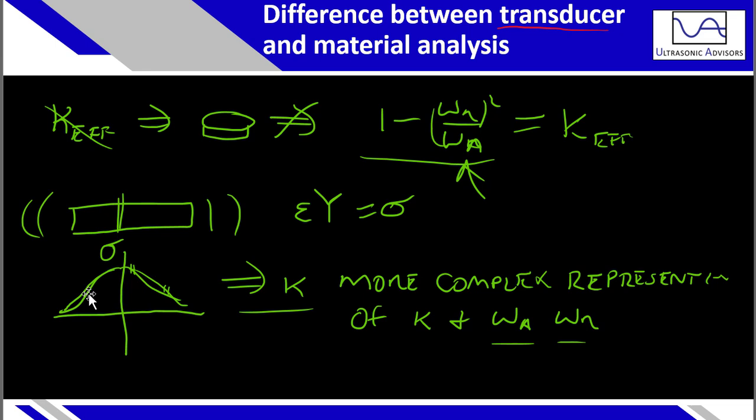And the general form, after you extract using the appropriate formula, which can be derived for a specific resonant mode, for example, in this longitudinal bar, assuming polarization in the thickness direction and driving up top and bottom electrodes, you'll have a coupling factor coming from this, known as k31, which is the electric field applied in the three direction, displacement in the one direction.